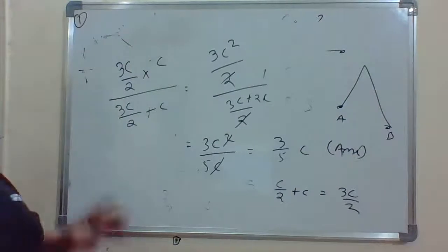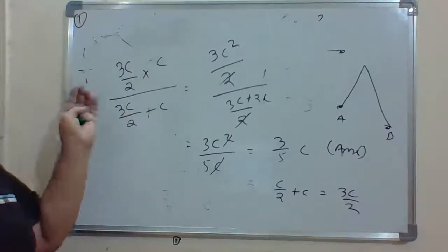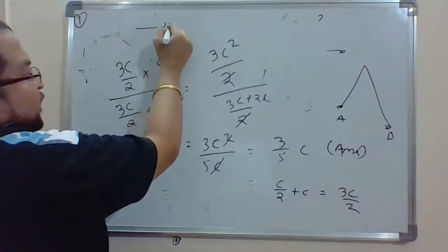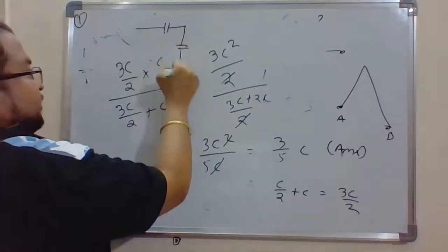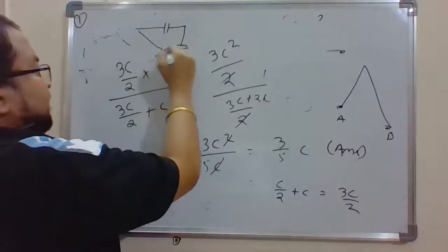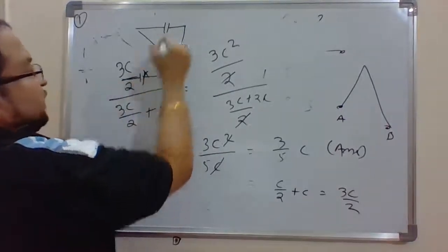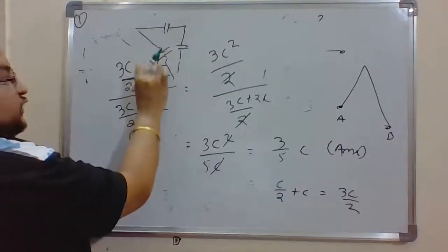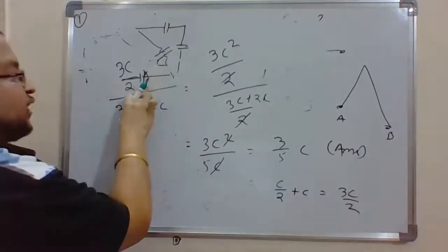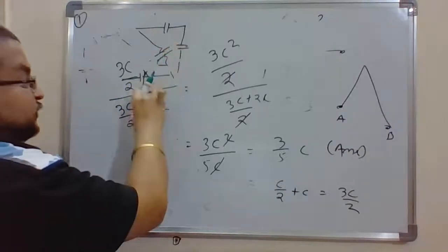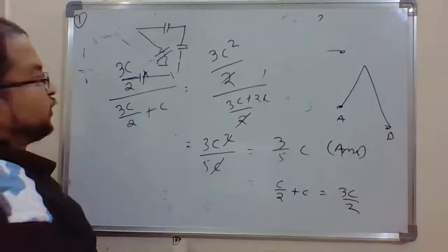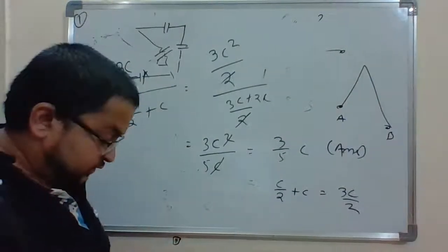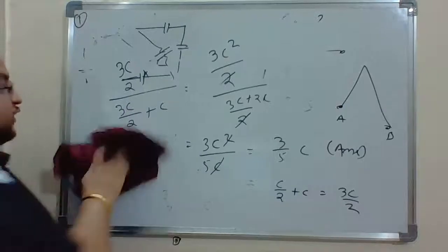Okay. So obviously when you are solving it in your entrance exam, it doesn't take this much time. We just quickly say it, right? That you have one here, you have one here, this is a capacitor, and this is another capacitor. These two are in series, so this is C by 2, C by 2, and this is C, so 3C by 2. So this 3C by 2 is in series with this, and we quickly do a multiplication. So in just a few seconds, you can solve the equivalent capacitance of this circuit.